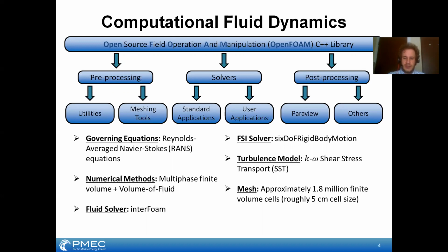And our mesh was relatively small by, say, industry standards for CFD at only 1.8 million cells approximately. But this was small enough we could run on not too many computational nodes in the university high performance computing cluster, run enough simulations to kind of develop this scheme and test it and make sure it's working properly. So in the interest of time, that was used.